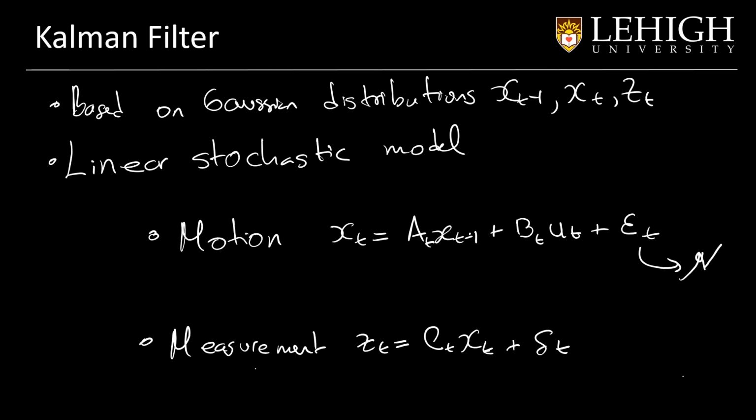In our case, we will simplify this, and we will just assume that the control input is the velocity, so we just need to multiply this by delta t, and we will obtain the desired state. The variables of the previous state are the variables of the new state, so this is the identity matrix, and we will keep the error the way it is.